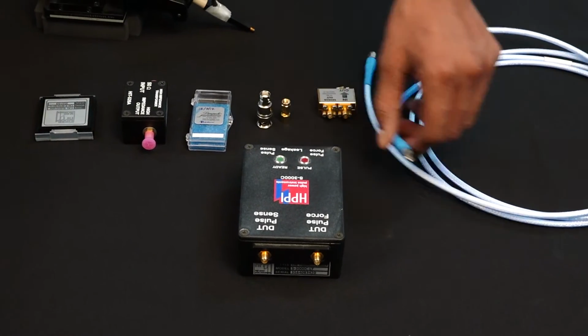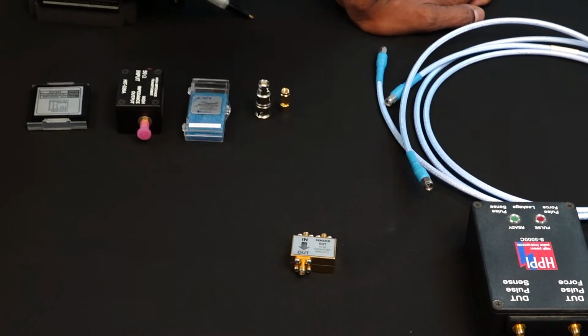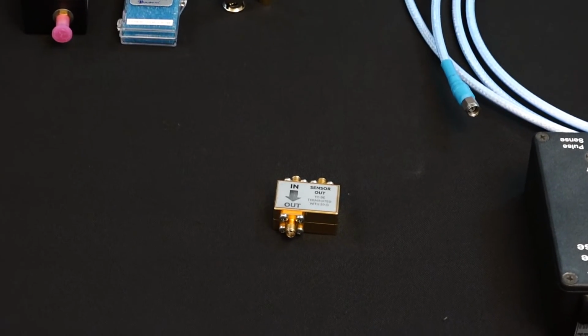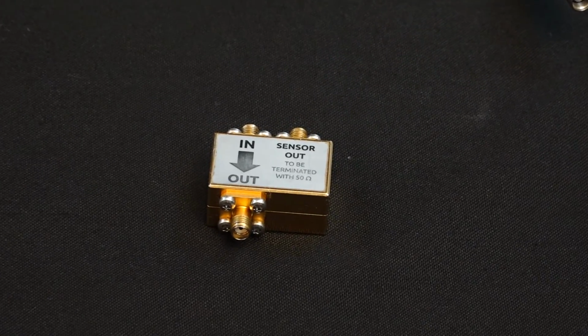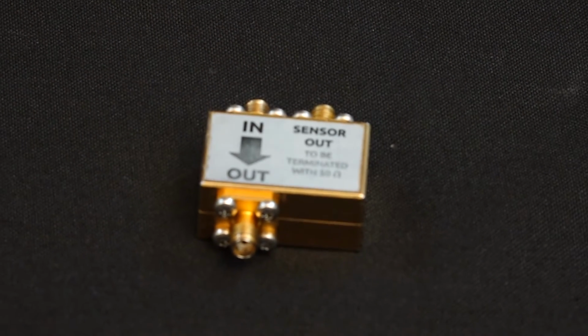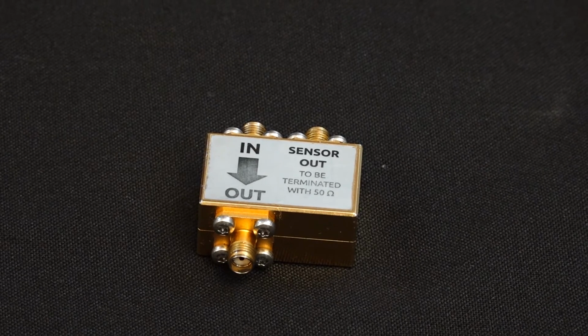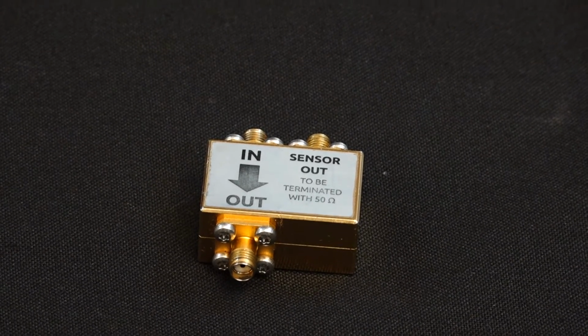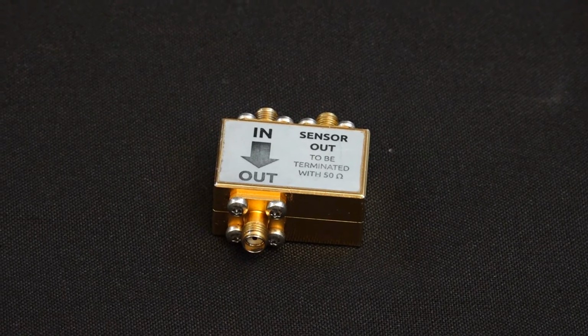The third component that I'll talk about is a current sensor. Now current sensor in its very essence is basically a current transformer. So basically you will have a pulse signal coming from the switch and the TLP generator to the current sensor. It will then get transmitted to the device under test, and the response of the device under test will then come to your current sensor, which will then be transmitted to the oscilloscope.